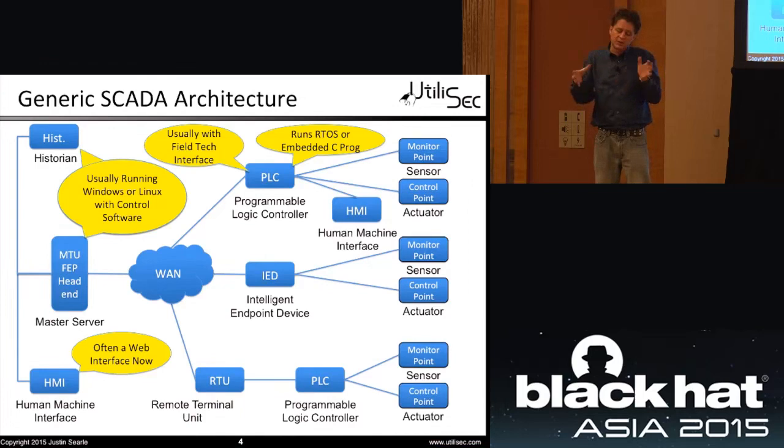If we want a term that describes a lot of those systems, we generally call them DCS, or distributed control systems. They have different needs. They usually are pulling information back from the sensors every 1 millisecond to 10 milliseconds on some of the faster systems, whereas SCADA is usually working at a resolution of pulling information back from the large network maybe once every 2 seconds or once every 10 seconds. So there's a very, very big difference in how we're actually working with these.